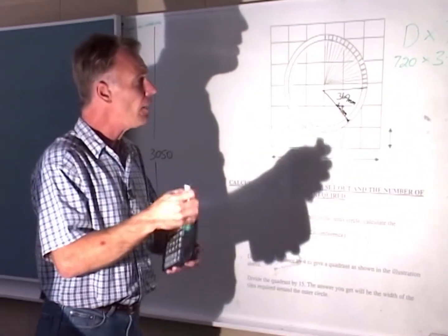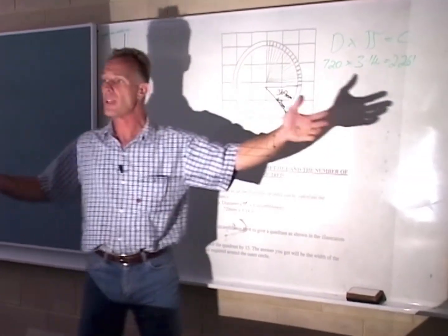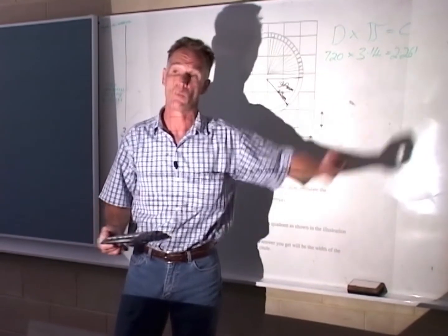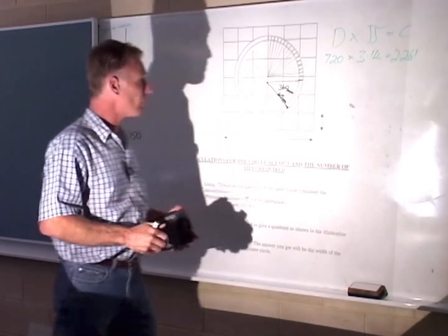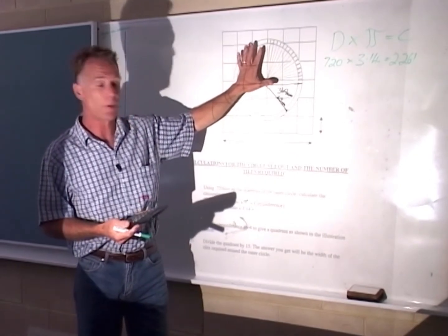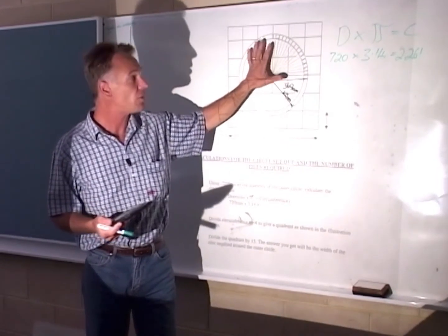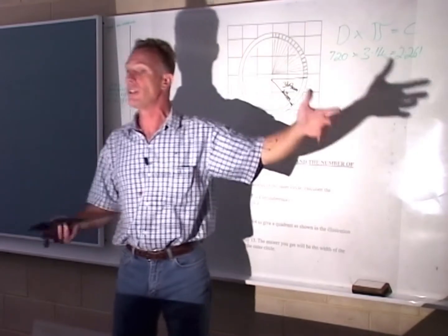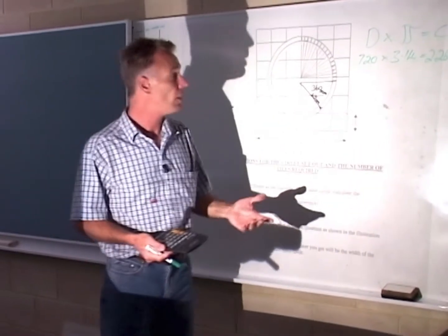Okay guys, if you were to take that circle, that outer circumference there, stretch it out into a straight line, a string, a measuring tape, whatever you wish, it will be 2.261 metres long. Okay, that's our circumference. Now, from there, as you can see by the diagram, and as I'm sure many of you know from doing these projects previously, you will work with a quarter of the circle first, for obvious reasons. Once you've worked out, calculated and cut tiles for 1/4 of a circle, you're really reproducing that same task 4 times for an end result.